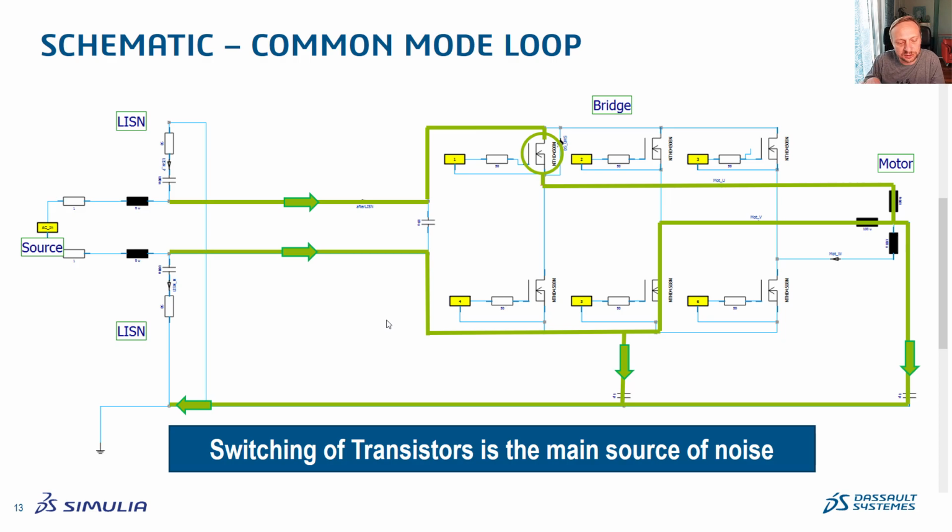Of course, I said that the two wires have a voltage against PE, right? So we have to include PE in the picture. And the PE is, of course, isolated from the electronics. That's its job. But there will be some parasitic coupling, namely capacitances. There will be capacitances in the motor. There will be capacitances from the board to PE and also from the cables to PE, so that the propagation of the common mode will mainly happen due to these parasitic capacitances.